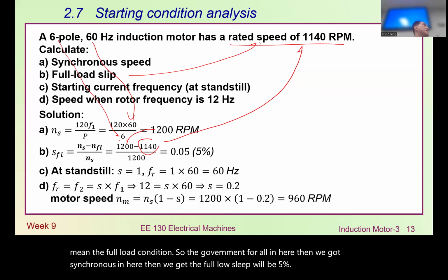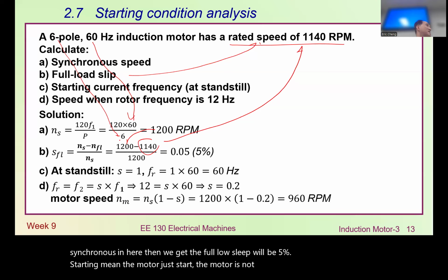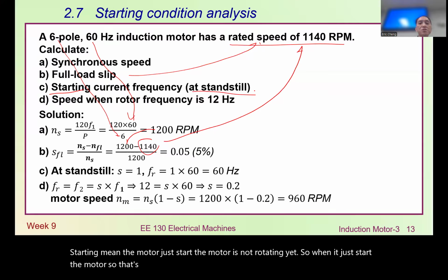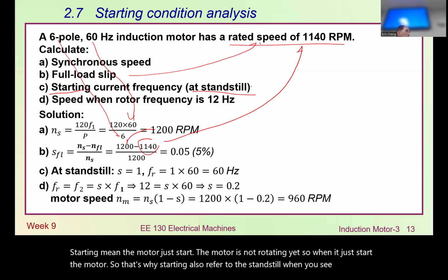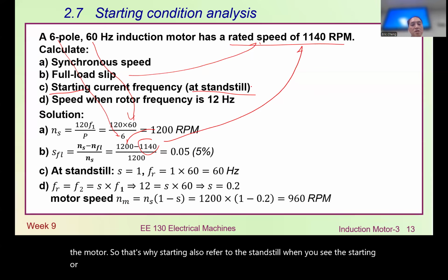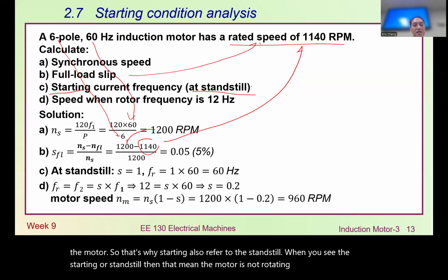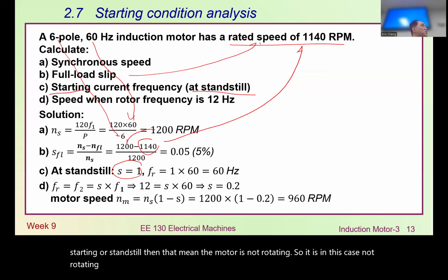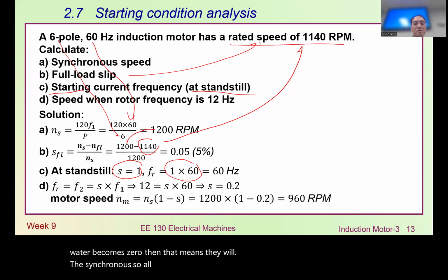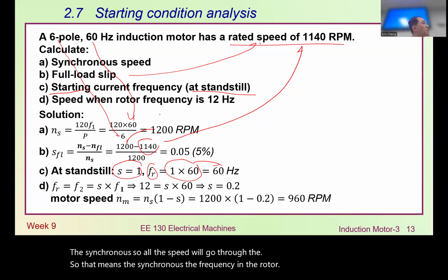Starting means the motor just starts, the motor is not rotating yet. So when we just start the motor, starting also refers to the standstill. When you see starting or standstill, that means the motor is not rotating. So in this case, not rotating, the slip, the difference between the synchronous speed and the motor speed, becomes 0, so the motor speed is 0 and the slip becomes 1. So the frequency in the rotor, or the starting frequency in the rotor, will therefore equal